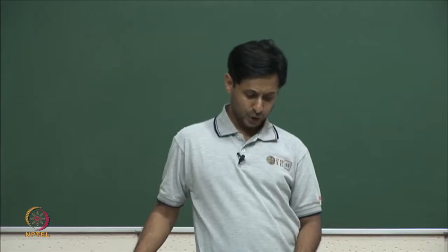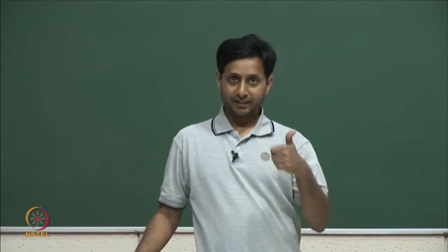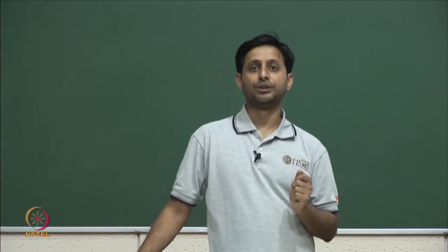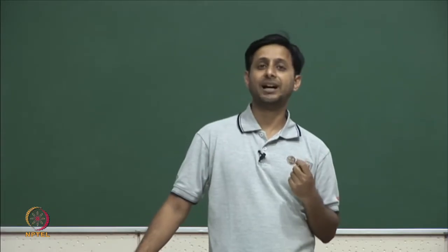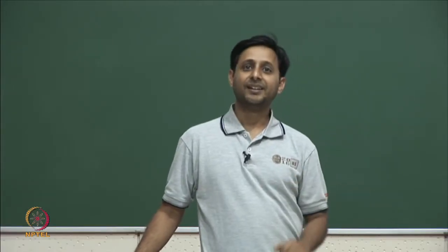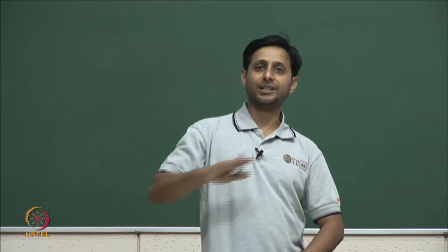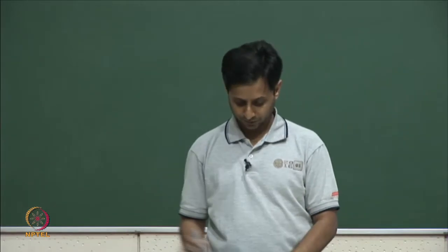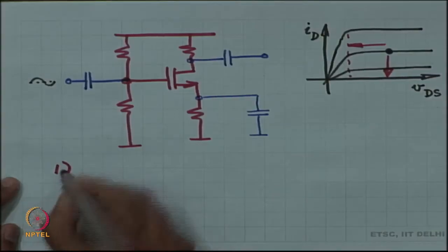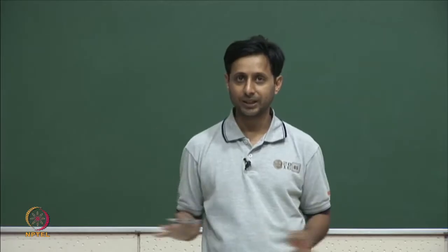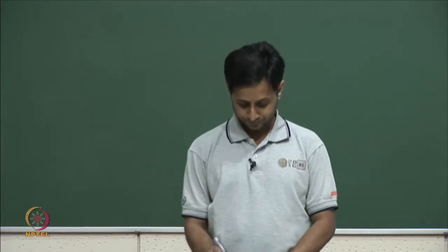So, you have to make sure that number 1, your device is in its flat region of operation, and number 2, the current through the device is more than 0 under all circumstances. So, these are the two extreme conditions. So, remember these are two and only two extreme conditions, everything is going to depend on these two.